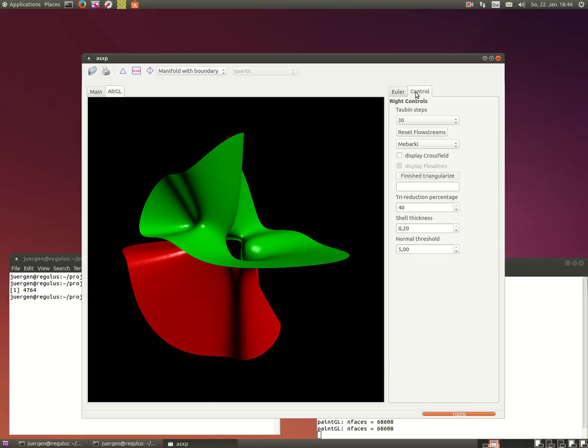So next to another possibility of the program, reducing the triangulation. Triangulation is done not only for display purposes, it is also the preliminary stage necessary for generating a 3D model of the surface suitable for 3D printing. For this goal, it is desirable not to have too many triangles in the triangulation because there are limits on the file size and number of triangles for model files for 3D printing, for example, the popular STL file type.